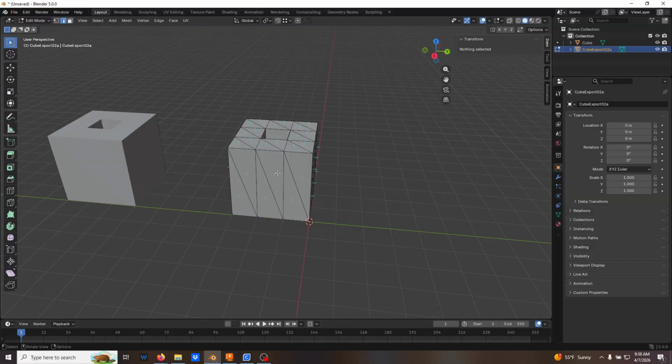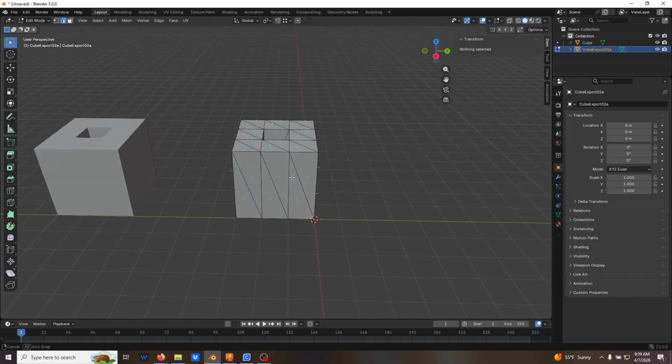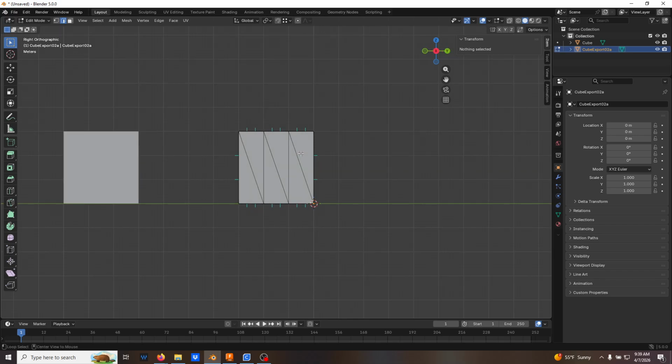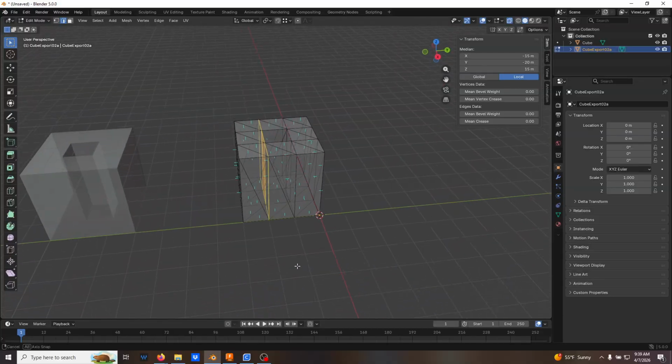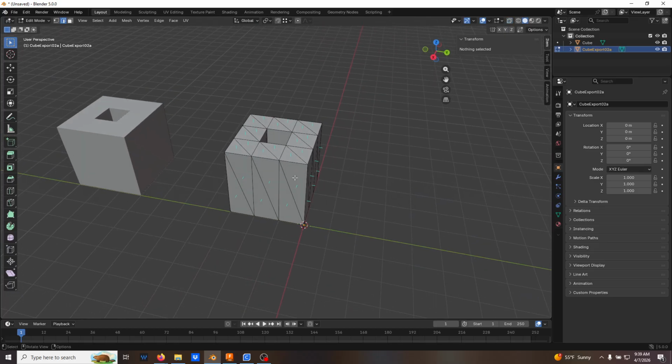It's still going to triangulate, because when you think about it, even though we're working in quads, any quad is going to be made up of 2 triangles, but the mesh here is a little bit cleaner and subdivided. If I go to the right here, Alt Z, and I wanted to select edges, I get a better way to manipulate the edges of it. So how you arrange and lay it out can be very helpful, but it's still going to just triangulate it.